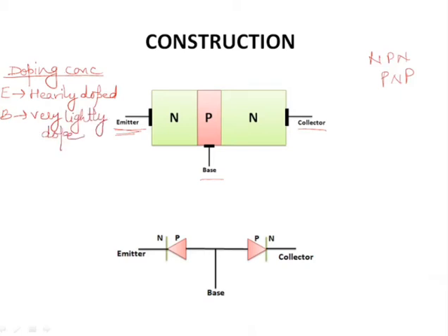Why is its doping kept very low? Because we know that base has P type of doping. This means it has holes as majority charge carriers. So as the electrons from emitter try to pass towards collector, we need very few electrons to get recombined with the holes, and maximum electrons are required to pass towards collector.